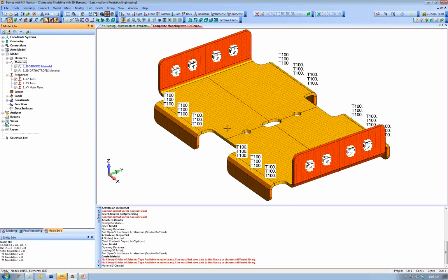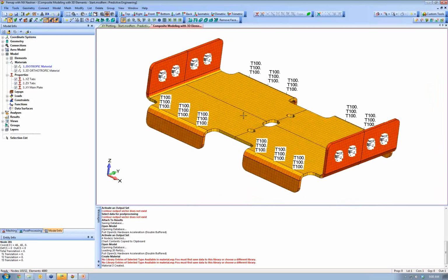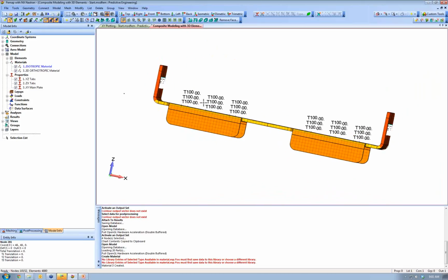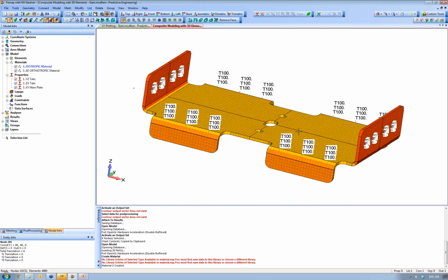I've broken this up into 3 different properties because if we imagine this as a composite part, maybe we're going to start out flat and we want to align our fibers in the global Y direction. Once it's bent, we think our stack direction is going to be different for each of these 3 tabs.